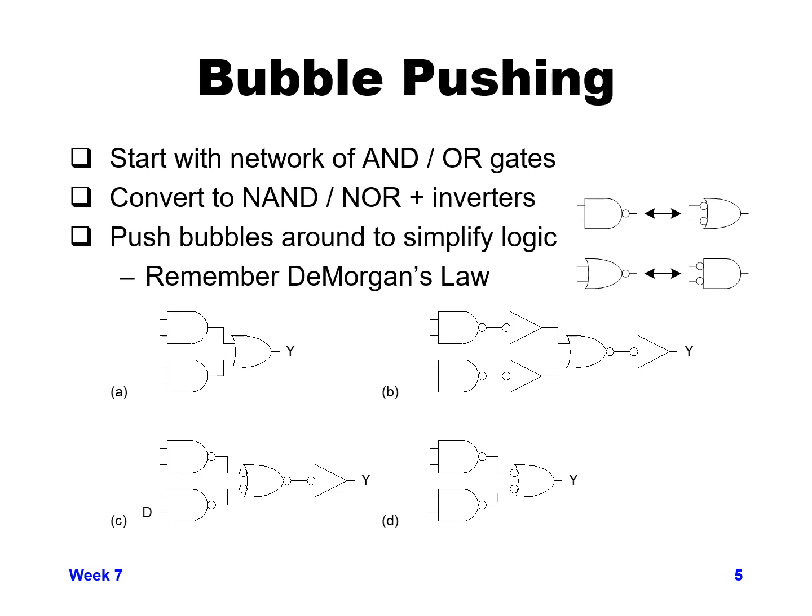Now of course that's 2, 4, 6 gates. We want to try and minimize that as much as possible. So when we take that and go down to part C of the figure in the lower left, what we can do is replace the inverters that we've drawn with bubbles that get attached to the NOR gate in front of the inverters.